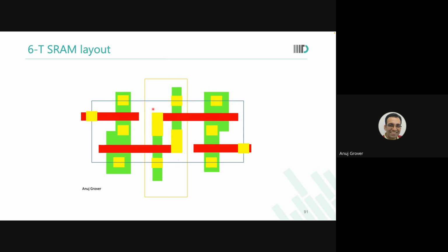And that has some semblance of long contact. It's a contact which you can stretch. Contact you can stretch means tungsten, and you can make wires out of it. So in advanced technologies, people have allowed use of LIL, local interconnect, to gain density.